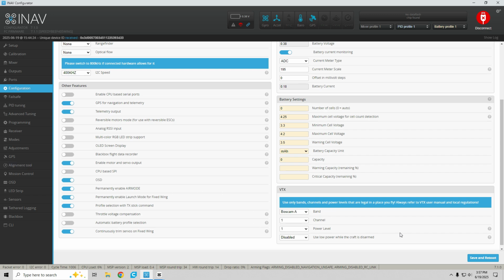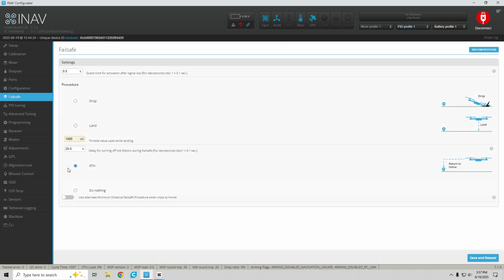I don't mess with my VTX down here. You save and reboot. Fail safe. You don't want to drop or land. I do return to home. And that's the delay for return to home. And if that's not selected, hit save and reboot.